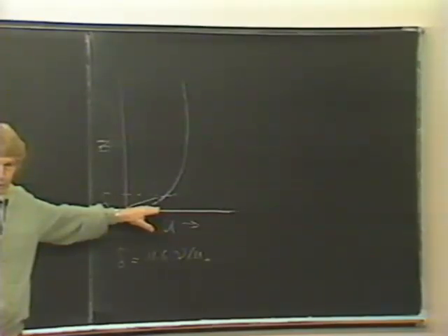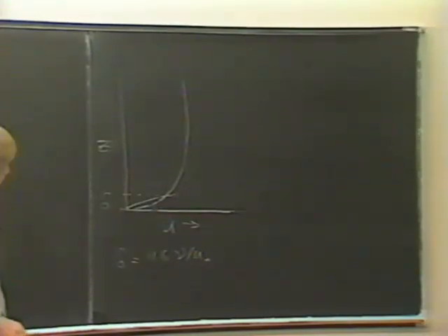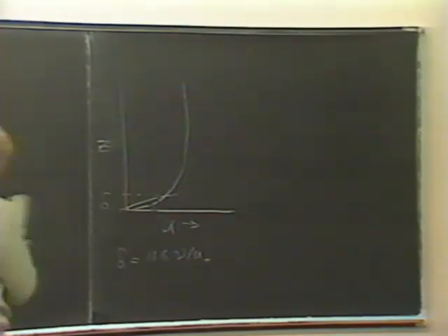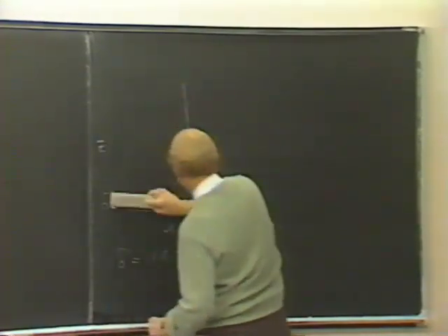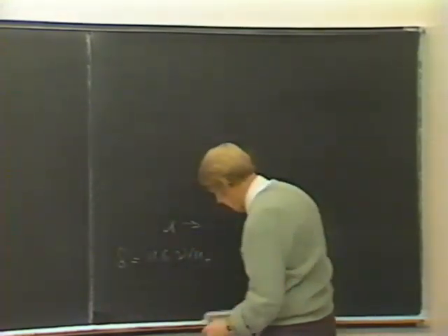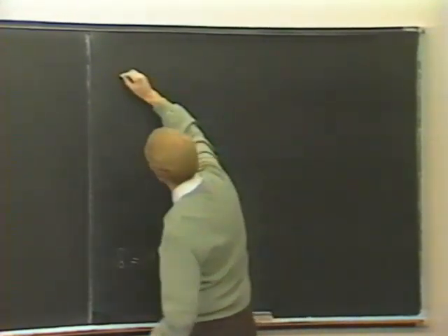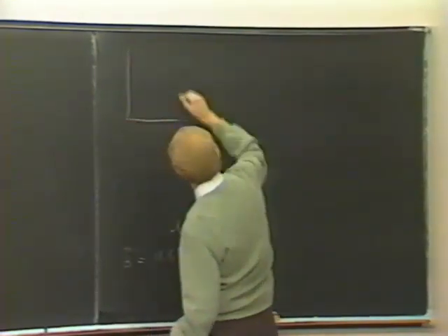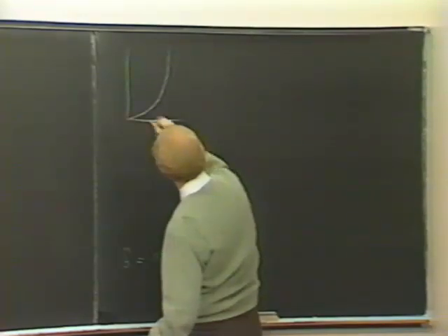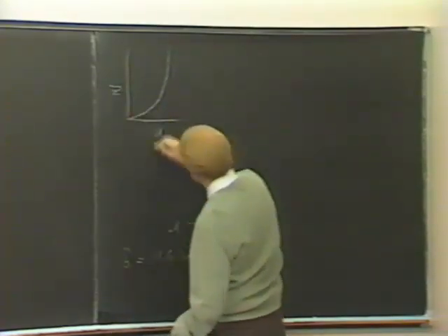So the stresses on their surface, except when they collide with one another, are very much lower than the stress on the surface of the bed itself, where the velocity gradient applies shear to the fixed aggregate. So we have both of these processes taking place. That is, particles touching the bed and coming off, and particles settling to the bed. But now our settling velocity depends on that breakup and reaggregation of particles that takes place in the bed.